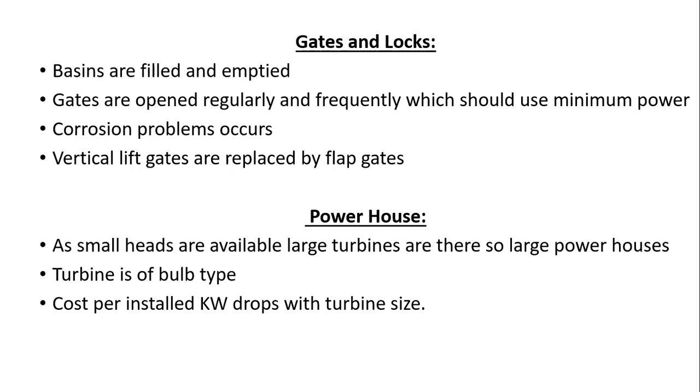Okay, because in this problem we cannot paint. There is no possibility of painting, because there will be erosion of the paint by water friction. There will be water friction at the gate, so the paint will not stick to the gates. So we are solving this problem by replacing the gates with cathodic protection.